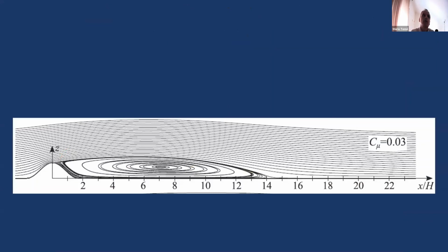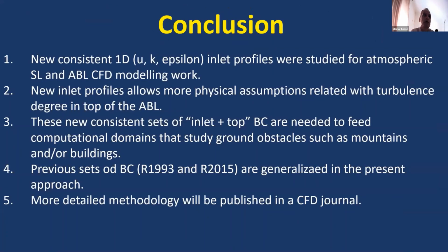And finally, as conclusions, I can say that we developed consistent inlet profiles that assure horizontally homogeneous profiles for U, k, and epsilon.